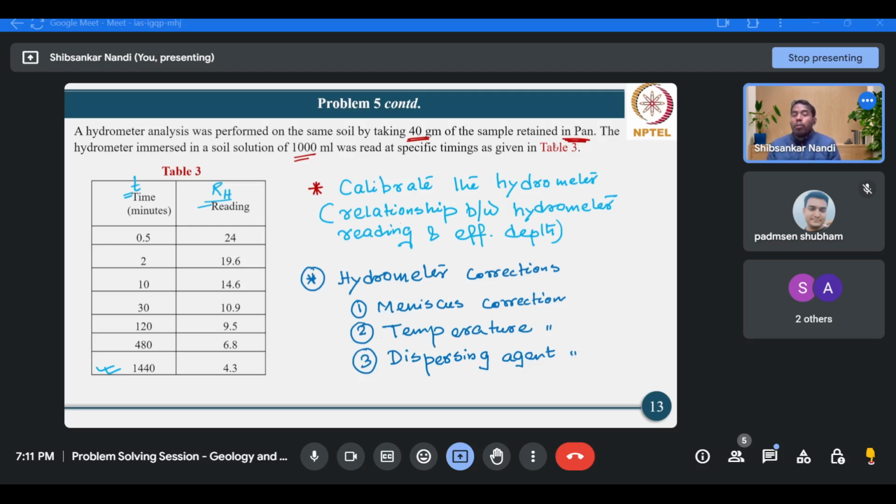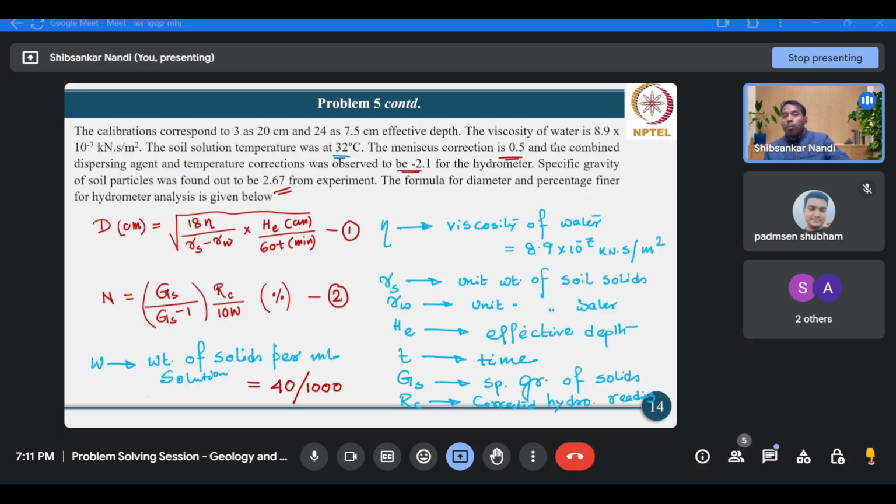However, when we draw the grain size distribution curve, we have to draw it on the total basis, that means out of 500 gram. Here we have performed the experiment only on the soil sample retained on the pan. How can we implement the correction factor for this situation?